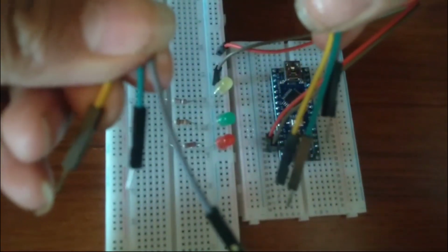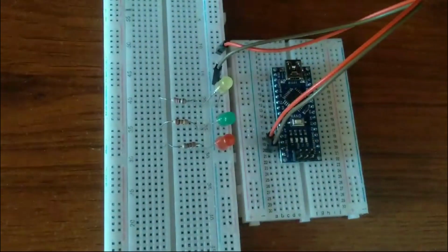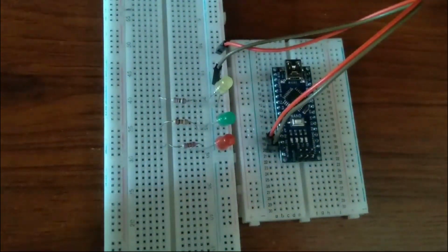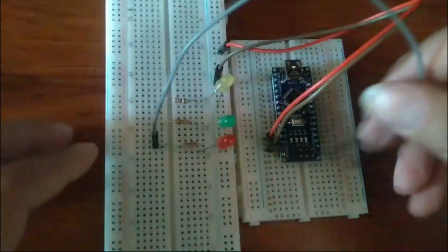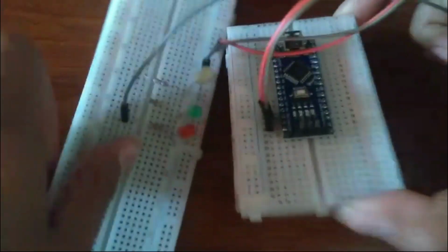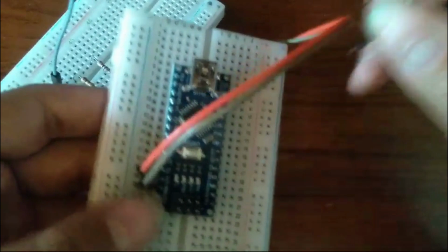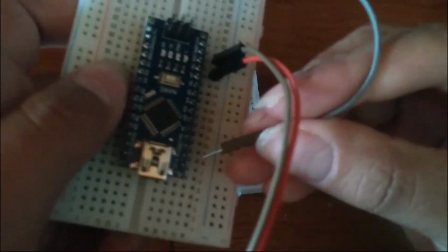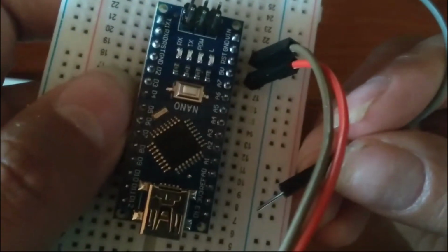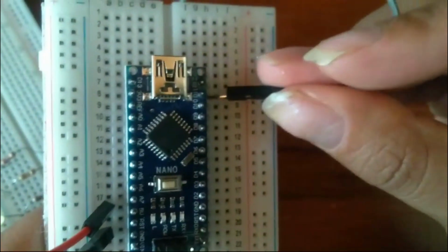Now once we have the circuit with the LEDs, it's time to connect to the digital ports. For that reason we have to use 3 more cables. Male, that is the name of these cables, right? So we're going to connect the first one in series with the resistor, and also we're going to search for the digital port. Remember that the digital ports are represented by a D. In my case I'm going to put it in D9. So here, look, you have to verify the D ports. Once you recognize it, you will have everything right? So remember D9, we have to search for D9.